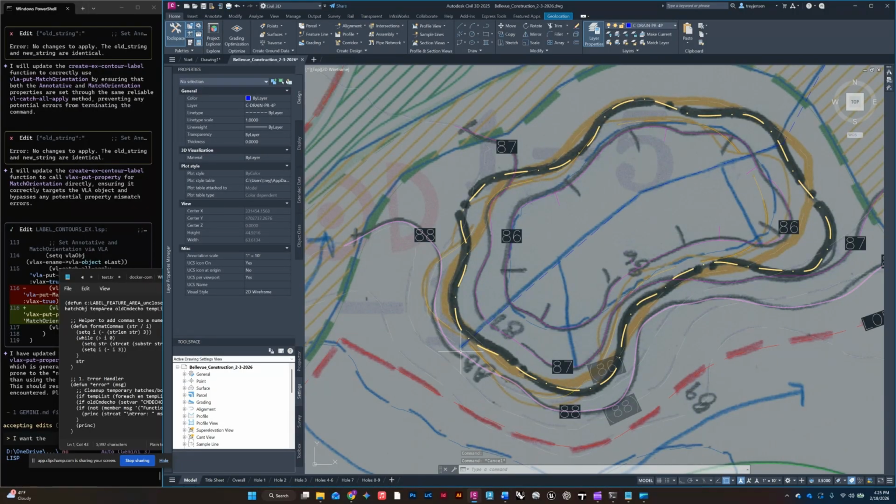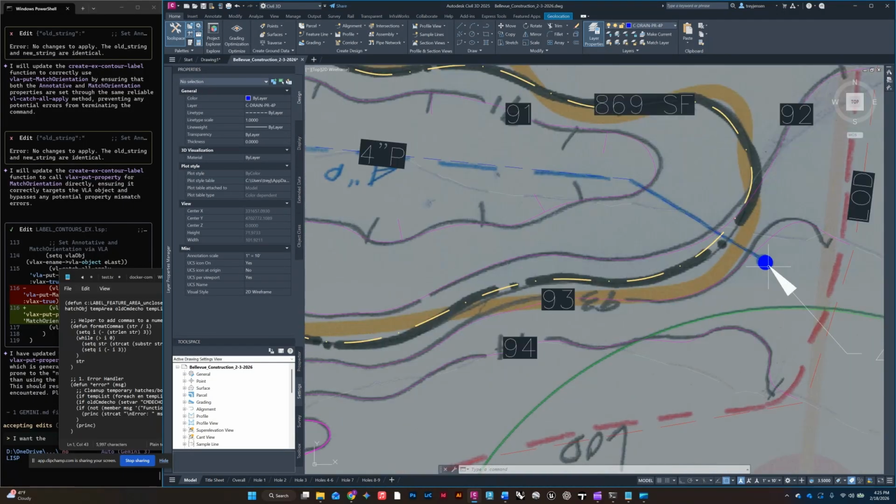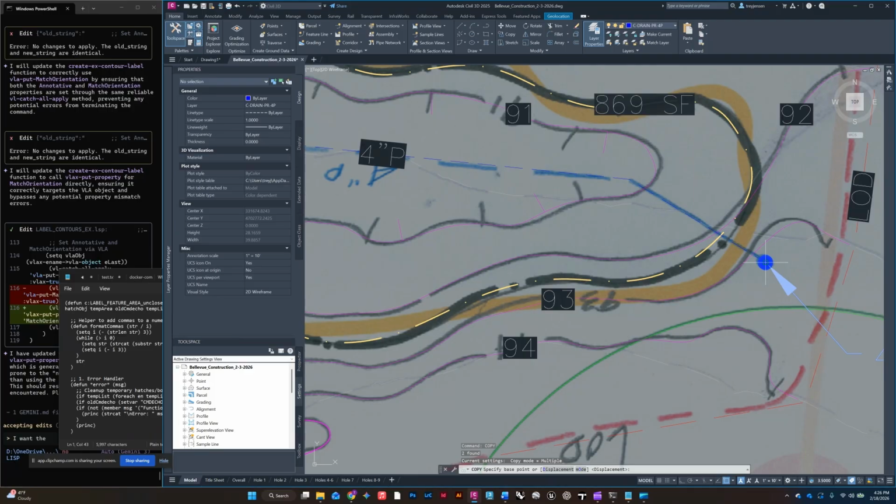Every bunker also is going to have a 4-inch flush out up on top, which is a point where you have an entrance to that pipe, basically. And so I have a block created over here. You can copy that, and you can copy the note. Select the center of it, again, using snaps.